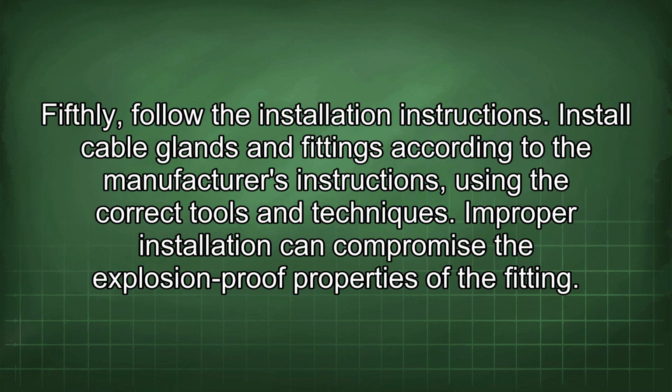Fifthly, follow the installation instructions. Install cable glands and fittings according to the manufacturer's instructions, using the correct tools and techniques. Improper installation can compromise the explosion-proof properties of the fitting.